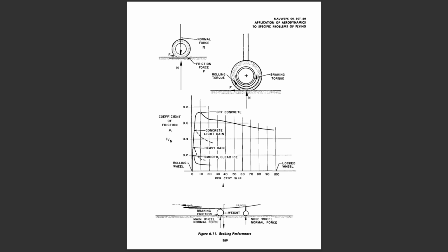Many factors can determine small differences in this peak value of friction coefficient for dry surface conditions. For example, a soft gum rubber composition can develop a very high value of coefficient of friction, but only for low values of surface shearing stress. At high values of surface shearing stress, the soft gum rubber will shear or scrub off before high values of friction coefficient are developed. The higher strength compounds used in the production of aircraft tires produce greater resistance to surface shear and scrubbing, but the harder rubber has lower intrinsic friction coefficient.